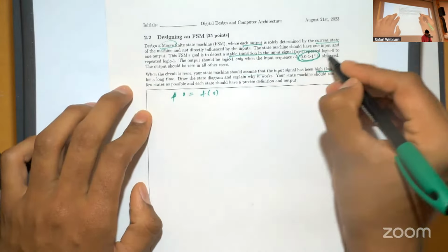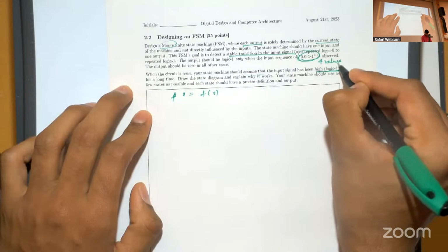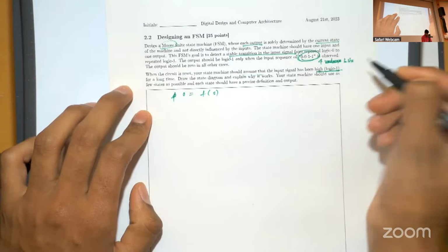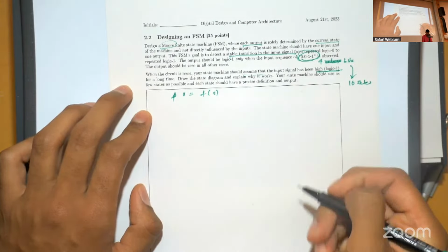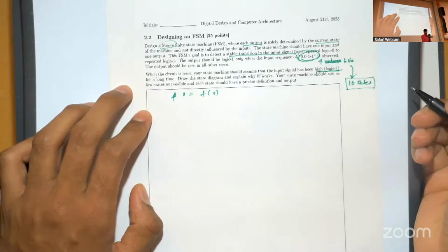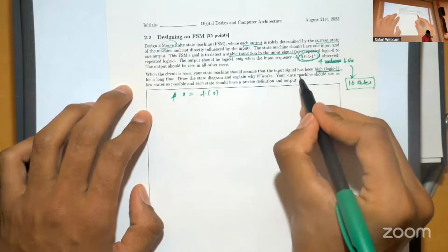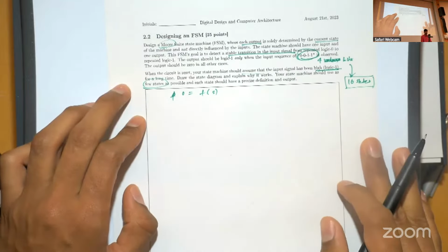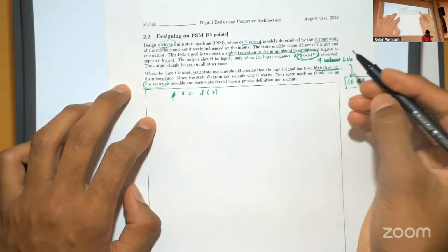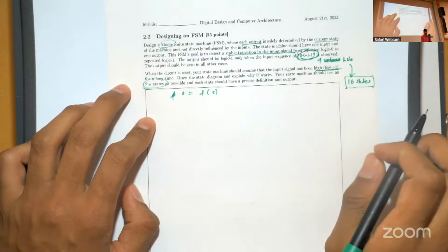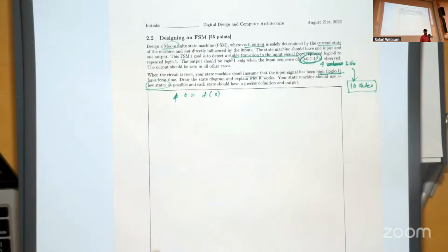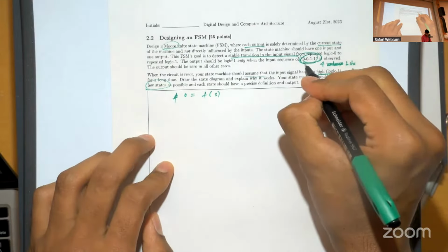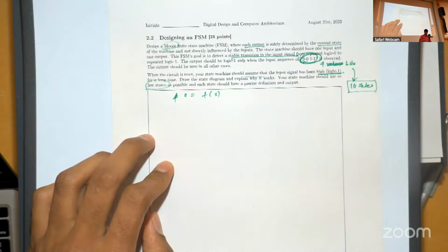You can see that you have 4 values here. 4 bits, which means that you can have up to 16 states, correct? This is the brute force solution, and this is not what we're looking for. We're looking for the fewest states possible. And what you will notice is that you can think of this in a sequential manner. So let's start with putting up all the states that we can think of, and we will come to the solution. Clearly, we need the state that identifies 0, 0, 1, 1.